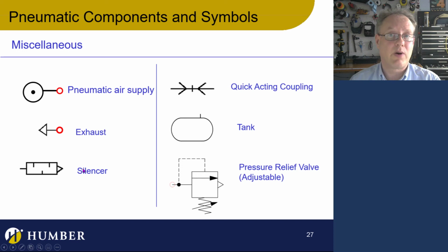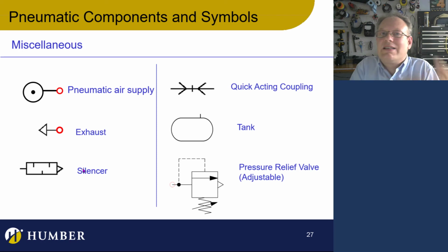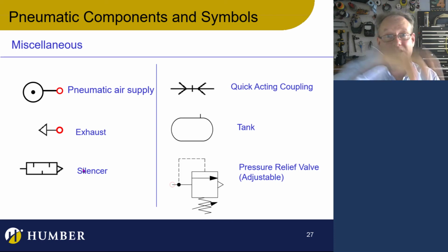Silencers are really very important. If you have ever pulled up beside a truck on the road, and especially in the summer, if you had your window open and you hear this psh, even the buses do that as well. Any large vehicle with air brakes is constantly pressurizing the system, and then when it gets too high, they vent. Actually, when the compressor turns off, it vents that extra high pressure that's in the cylinder head. When you turn any compressor on or off,